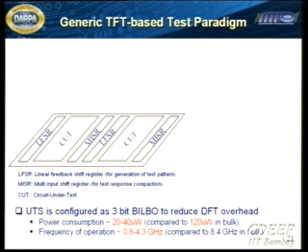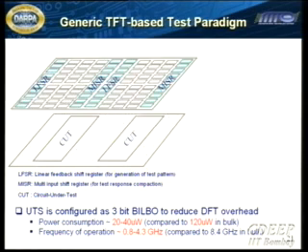And so those are there in the circuits, and one can potentially think of moving all these LFSRs and MISRs into your TFT domain, along with all these extra unit test structures that I've been talking about, to test or verify these underlying CMOS circuits.